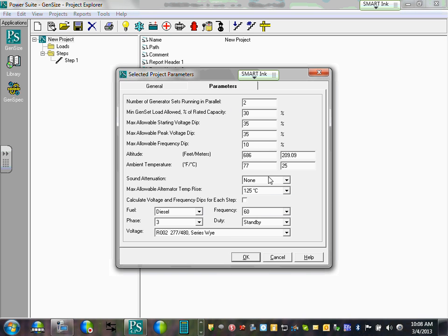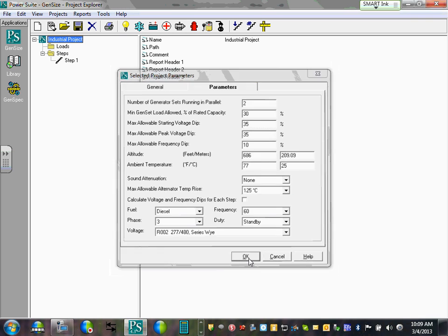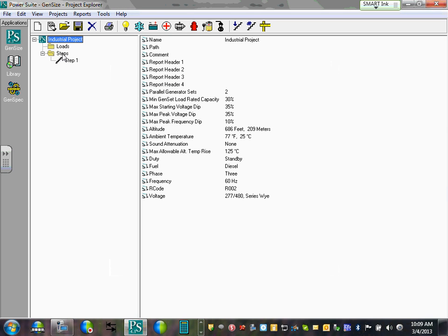Standby. So everything that we size is standby. We don't size for continuous or prime. If you guys remember when we went to Cummins, when they say prime means they run. Standby, they basically run, I think, 100 hours or less a year. That's what the standby is. Then if you go prime, they run more than that, and continuously. So we're running standby. Everybody got that one? Okay. Then, next. So we got the parameters of my generators.